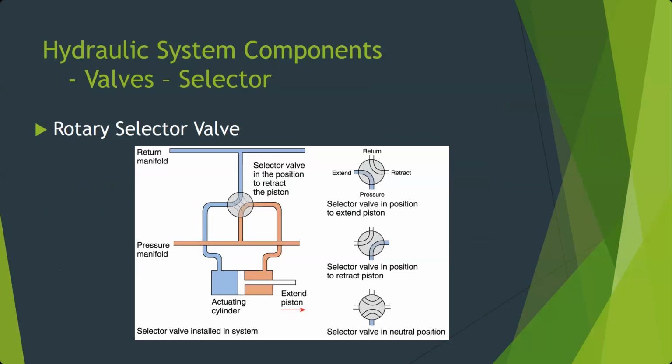When we retract it, when we move this actuator to the left, we have to have somewhere for the fluid on this side to go, on the left. And so you can see that same valve is also porting fluid up to our return side. If we rotate this valve to the other direction, what's shown with the dashed lines, that would route pressure to the left of the cylinder. But we have to allow that fluid on the right side of the cylinder to return,